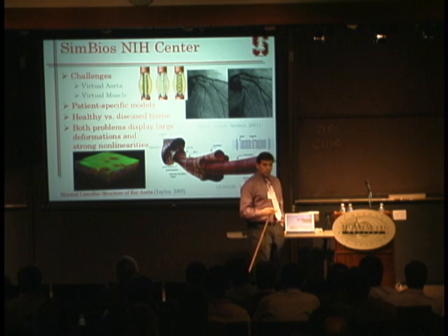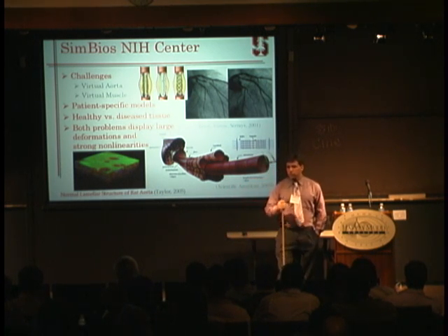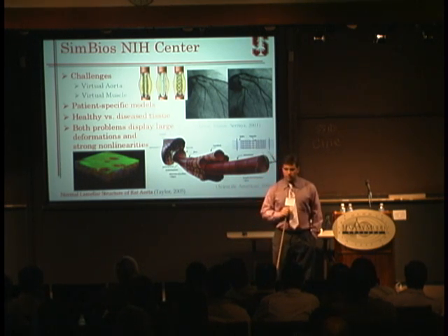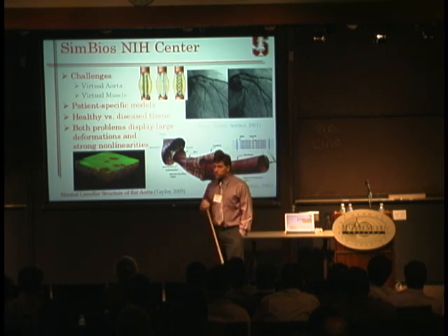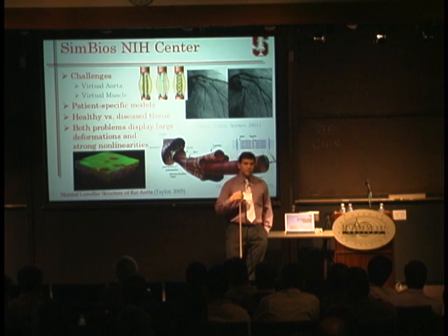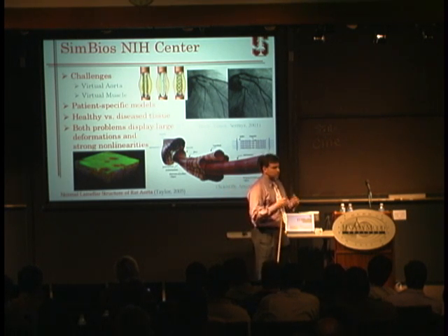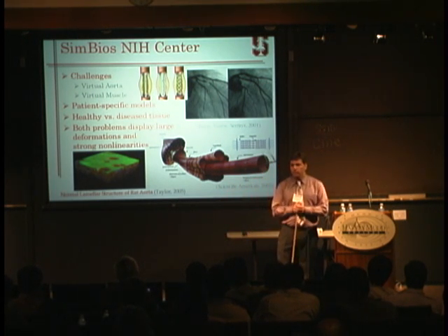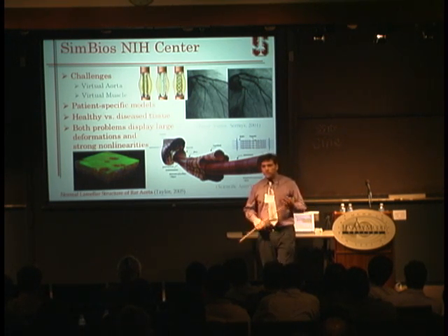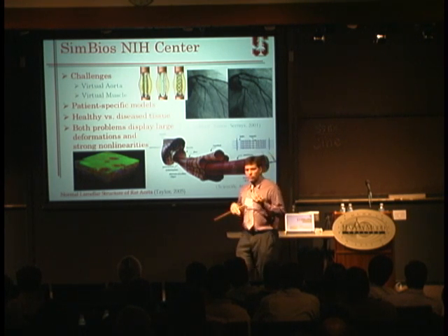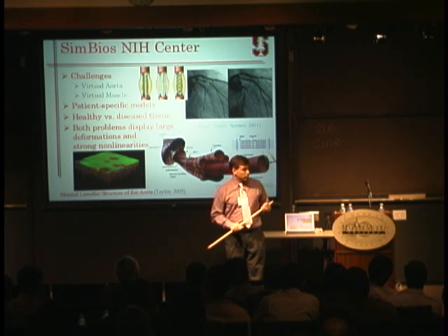When you do that, you go well beyond the range of nonlinearities in the material. You need to account for the large changes in shape that you have and, to give you a pictorial image, for the large changes in the distance between atoms or the arrangements between atoms that will change the constitutive behavior or the stress-strain response that you will measure.